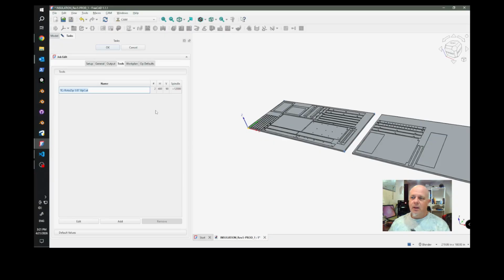I have a production ready machine. It's an older machine, a dumber machine, but it can handle 700, 800 inches per minute on the speeds. That's really fast for a little shop machine. If you have a little desktop machine, keep your speeds low. Start at 100 inches per minute and see how that feels with your tooling and the rigidity of your machine.